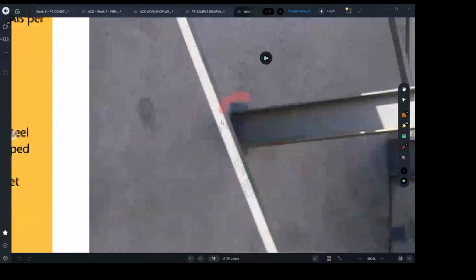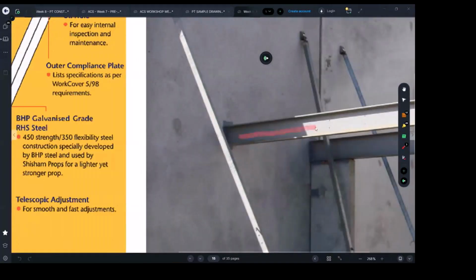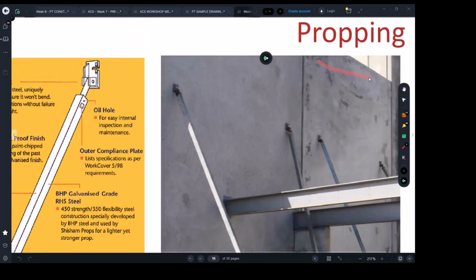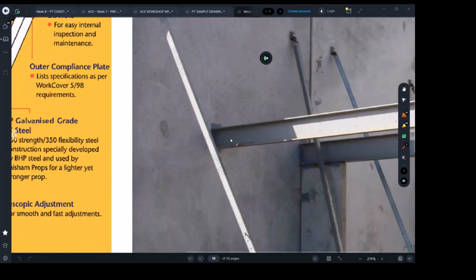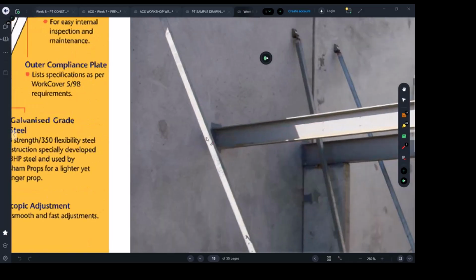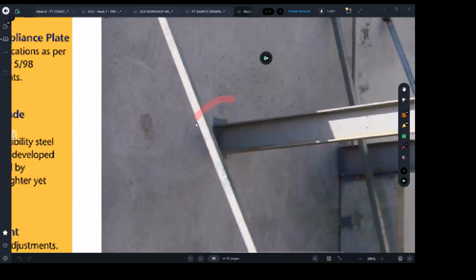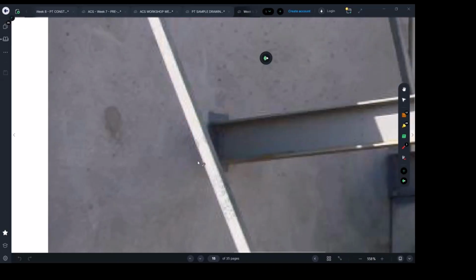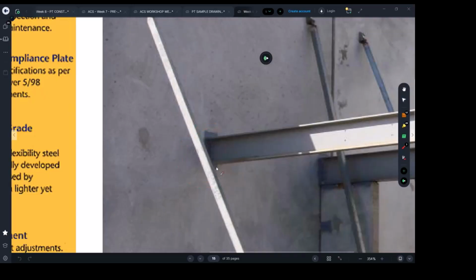Now, at this point here, that's where we're connecting a permanent steel beam. This beam maybe forms another floor in the building. It looks like the panel is higher, so the roof is somewhere here, but this basically forms the floor, maybe a first floor. And how we connect those steel beams to the wall is by either using the same thing, the ferrules I was talking about, or sometimes we can have a cast-in plate with U-shaped bars embedded in the wall. And all these kinds of components are pre-placed in the formwork before pouring the concrete for the panel.